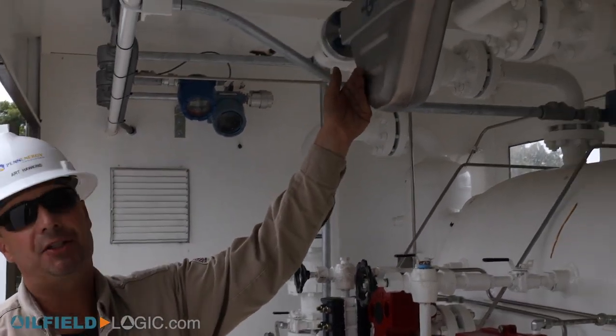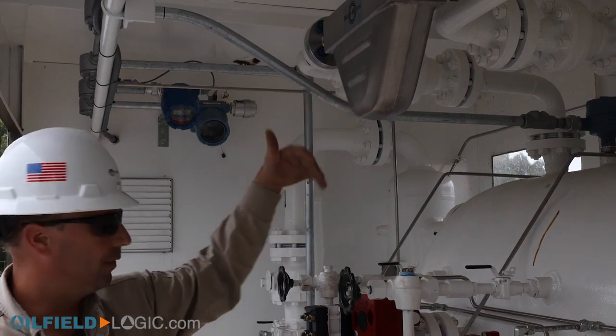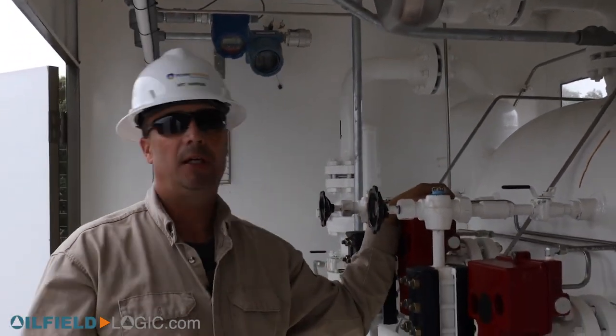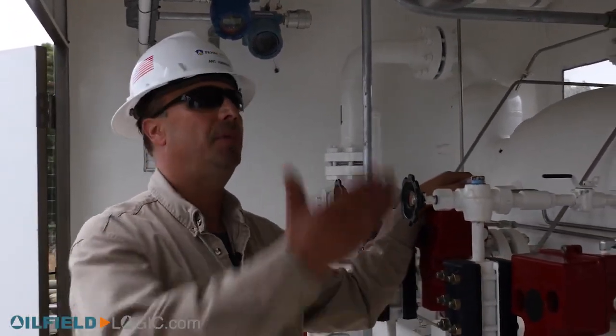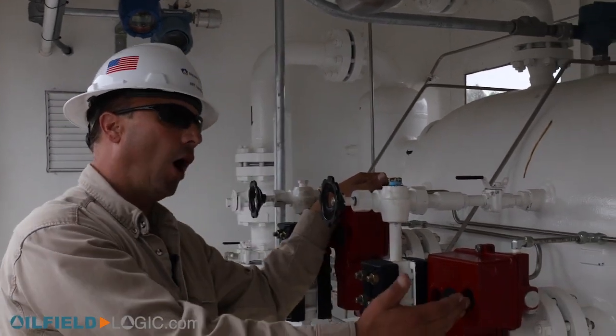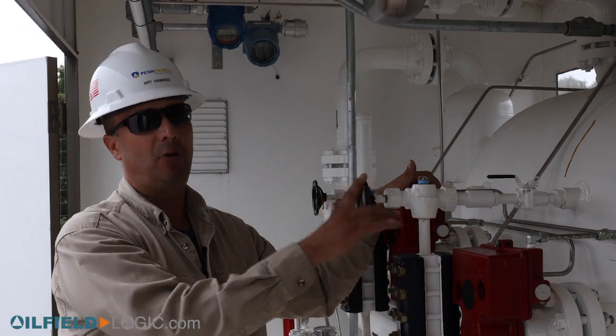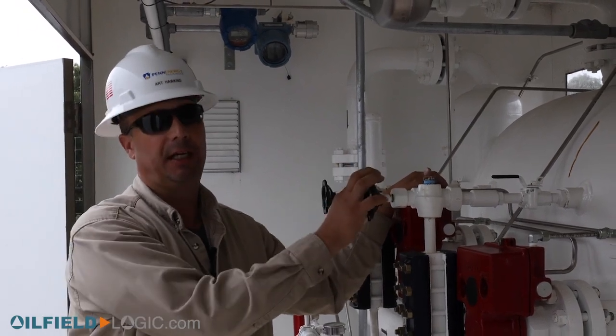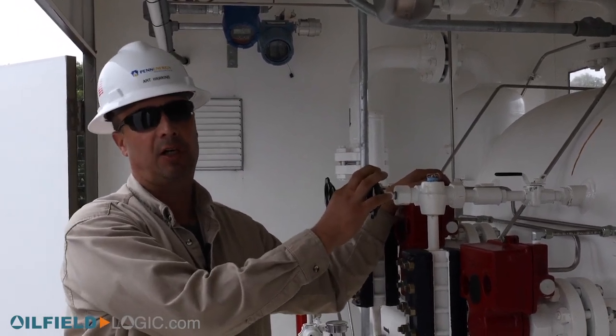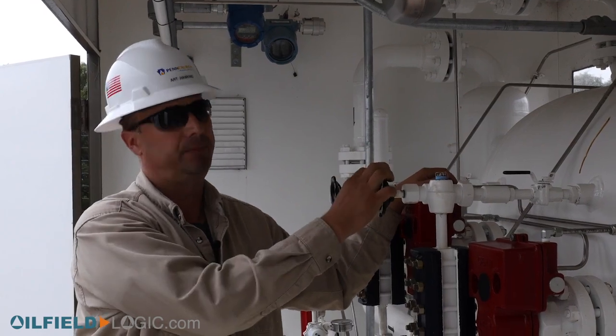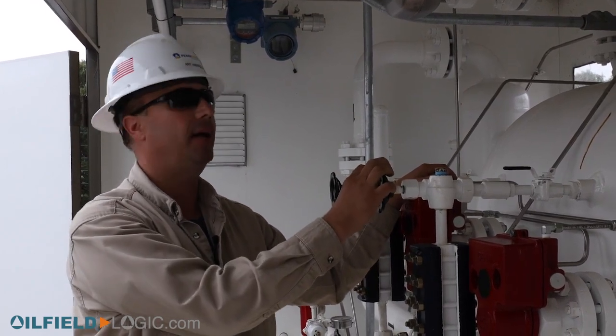This will track density of the condensate. If we have a dump hanging open, it's going to give us a low density alarm. If it carries water over to the oil, which we don't want, that'll give us a high density alarm. That will actually shut us in. Again, an operator will get an alarm and he'll come out and address it, try to figure out what we need to do to get back online.